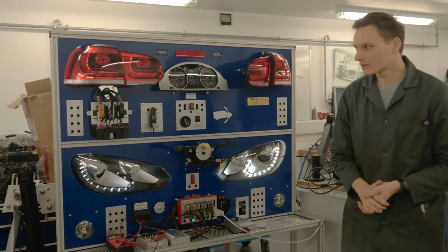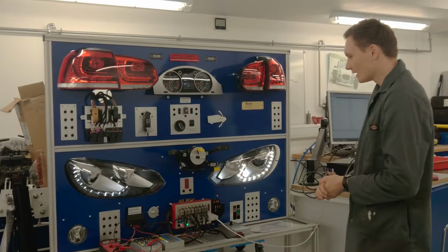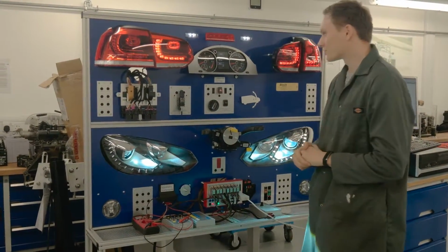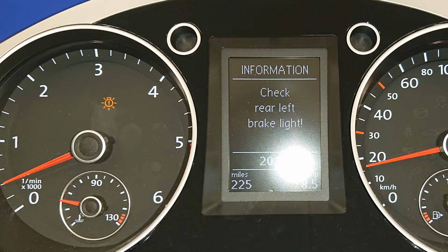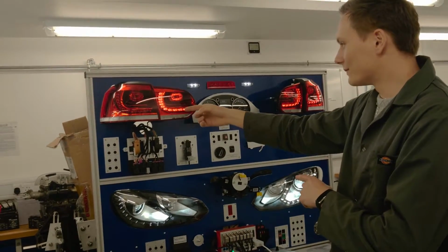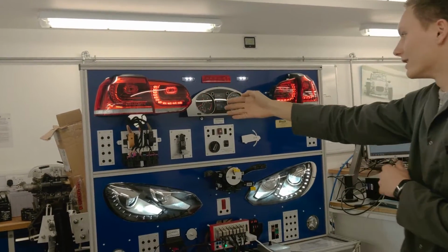We have been given a fault and we will be trying to solve it. So if I turn the car on and the lights on, I can straight away see there is on an MFD, and it shows a light bulb with an exclamation mark on it. So that indicates that somewhere there is a light bulb off, and also on the main screen it says the brake light bulb is not working basically. So we do a visual check. It's clearly shown that the bulb is not working.